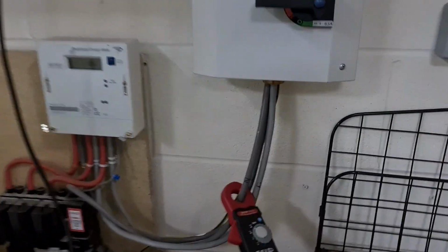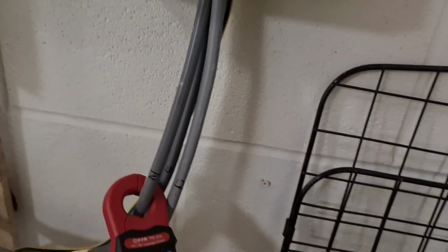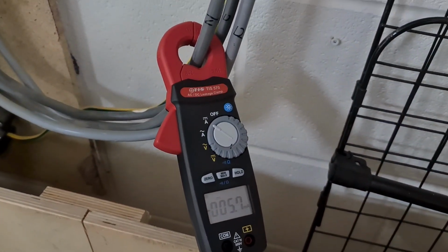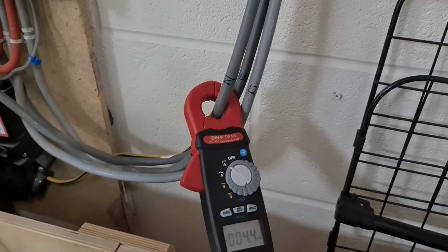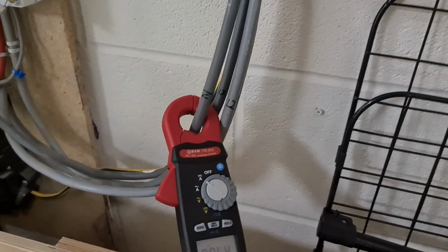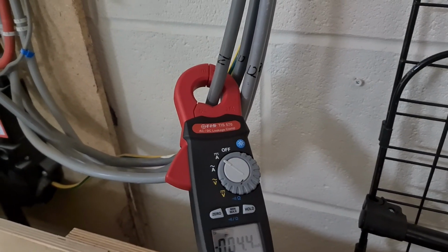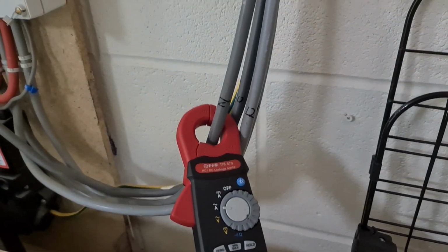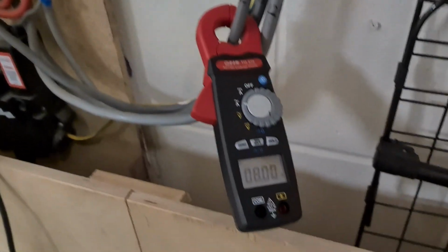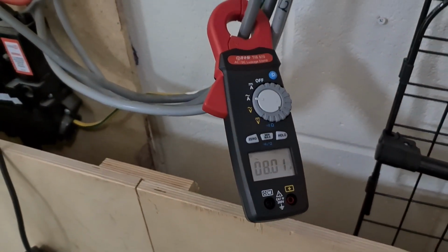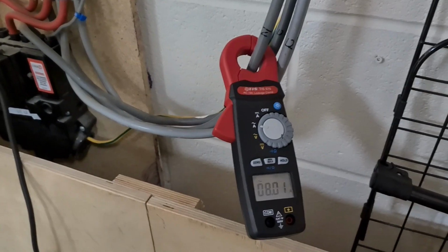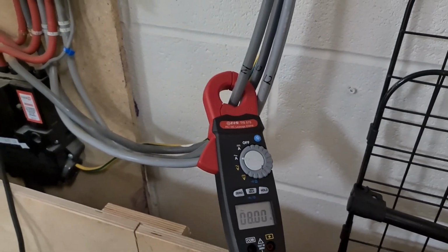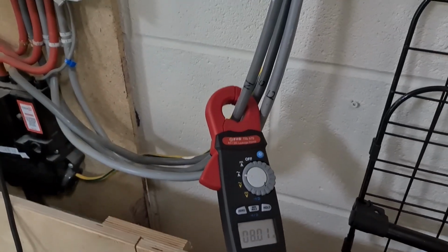You can see at the minute I've got my little TIS leakage meter on, and I'm looking at DC current for the time being that's flowing through the neutral conductor, and you can see there it's sort of around 4 or 5 milliamps. If we have a look at AC, this will just show you the current flowing in the installation. We've got about 8 amps, and primarily that'll be the electric heater, which I've got set to maximum right now over at the other side of the office because it's freezing. So we've got that there.